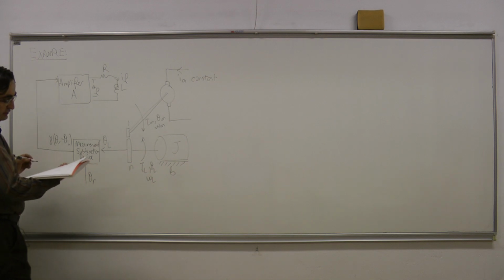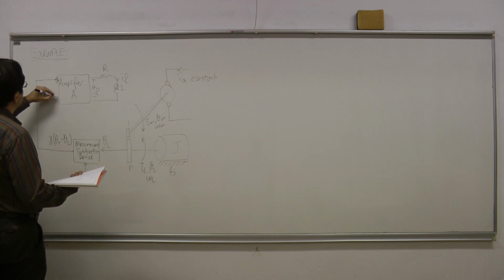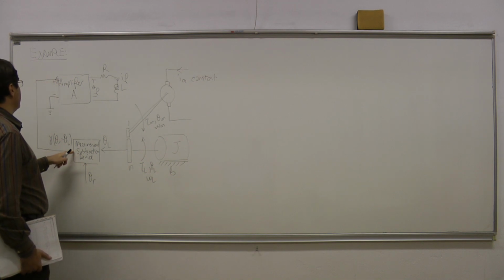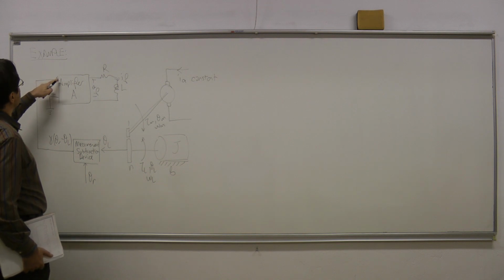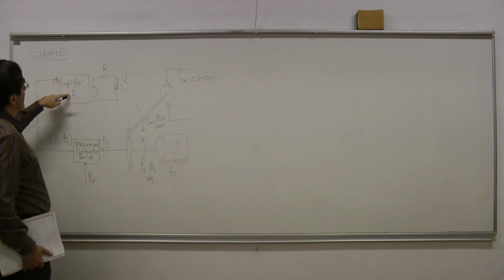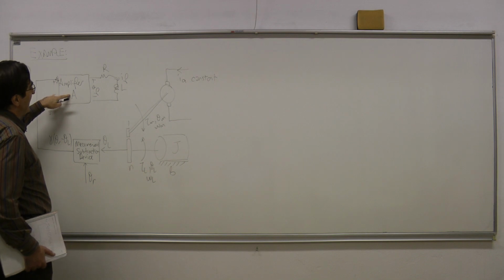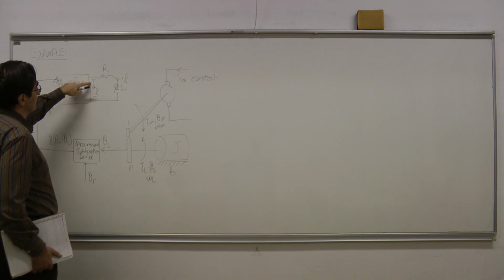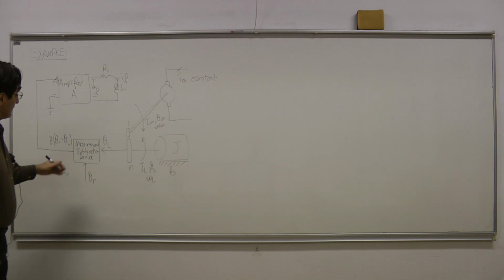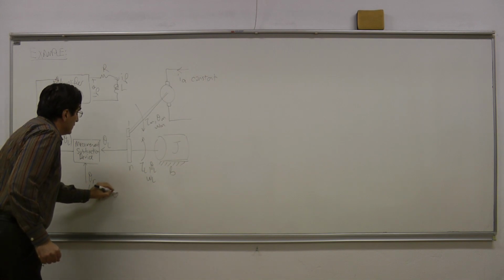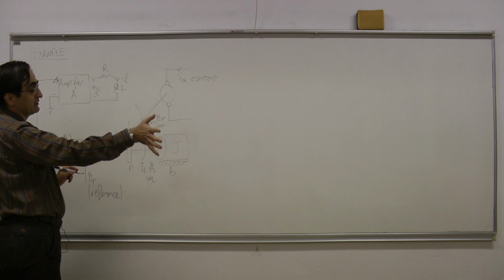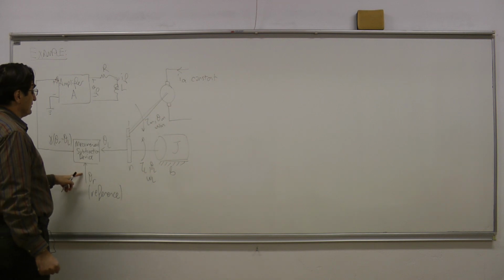And here this is connected to the amplifier. So the amplifier is usually shown with these letters here. I have connected the measurement subtraction device, and the result of it is connected to the amplifier, which means that there is a voltage coming from here and it is going to be amplified by the coefficient A, and the result is going to be our field voltage variable. Okay, so when I look at this system, this theta r is a reference. So I want this load to stay at a single theta value, at a single angle value, and this is the desired angle value.